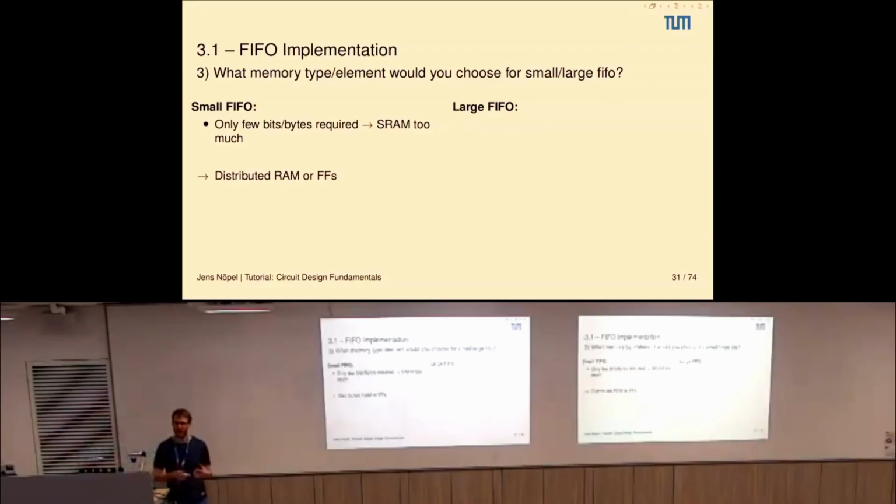You need sense amplifiers for that, and this only makes sense if you have a certain amount of data you want to store. So think of it like SRAM is heavier and suitable for a lot of data, more data than flip-flops. So here it definitely makes sense to use flip-flops.